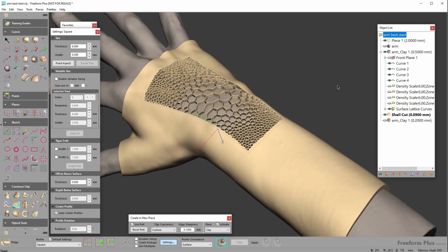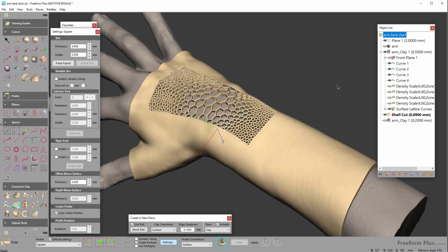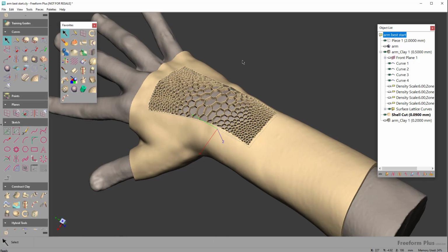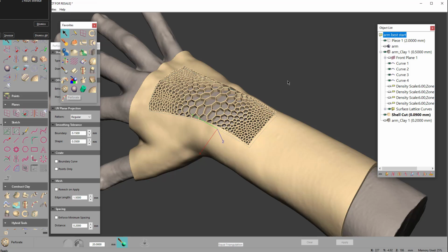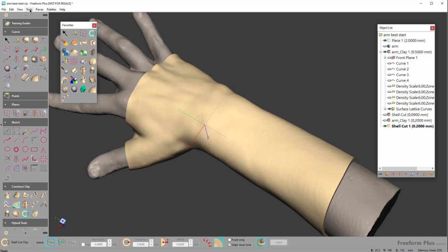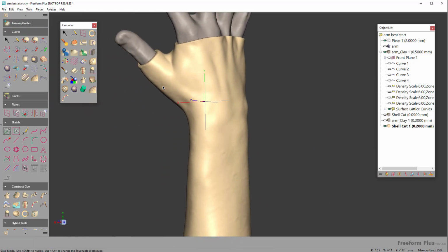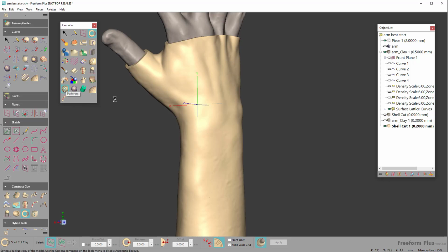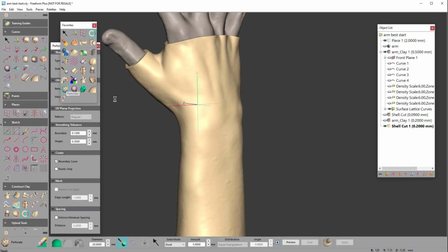So now let's look at another piece of functionality called Perforate. So with Perforate right here, you can lay out points upon a surface and poke holes in it. So that's what this tool does. We'll go ahead and create another model just to show the difference here. So we'll go ahead and turn that guy off. So now that I have that brace, just the repeat of the same brace that we talked about before, we have this Perforate tool, which is really neat. Perforate has some similarities in the initial steps here, where you can select an area and perforate that region.